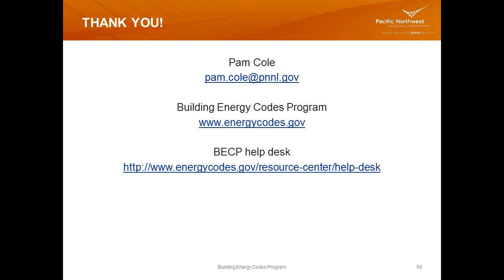Here's another question that came in. When it comes to slab on grade insulation, it is only applicable by zones. If I'm in climate zone 3A, I will require slab insulation only if it is a heated slab. Is that correct? Well, it depends on what code, for one. And then if it's heated, in the most recent code, there is a footnote, but that's for the insulation and fenestration table.